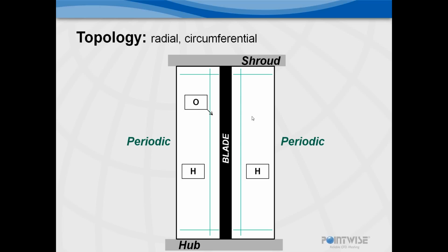If I turn on the horizontal lines, they delineate the boundary layer region I want to get at the hub and the shroud. So you can see without fillets, getting an H block in the corner region is pretty straightforward. It clearly matches up with the H block idea.